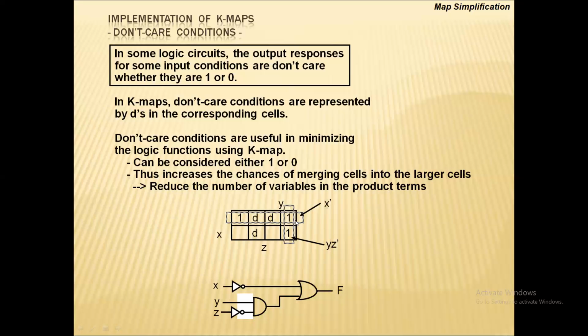Genuinely, in this type of situation, we should consider this. But you see here is one more d. If I club this, I get nothing because it is don't care. So in this situation, we will not take it. According to our convenience, we have to take care of the don't care conditions for pairing. While coming in the succeeding sections of the combinational logic circuits, we will apply extensively the basic rules of the K-map and the most simplified circuit we will get using K-map. Thank you.